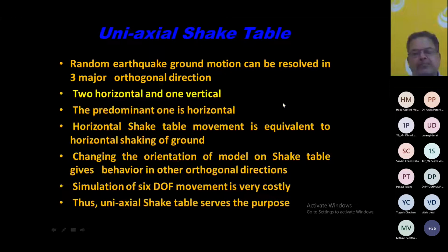So we come to another part. I told you that the shake table has 6 degrees of freedom, right? The 3 translations mean X direction, Z direction, and Y direction. So 2 horizontal directions, 1 vertical direction, right? And 3 rotations. Generally, the rotations are not important for a normal building. The rotations we have to consider when your structure is too long, right?